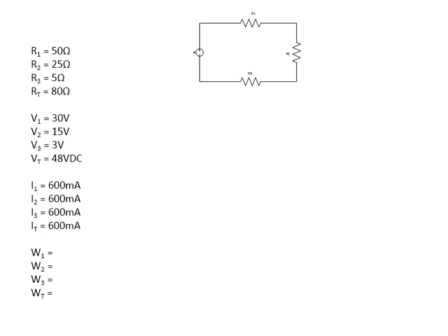The next step we'll do is to find the power for the circuit. That's the amount of work that we can do. And to do that, we'll take the 48 volts applied and multiply that by the circuit current. And that's going to give us 28.8 watts.